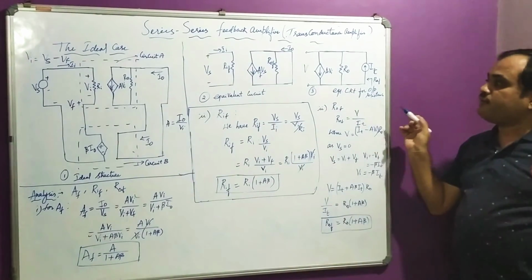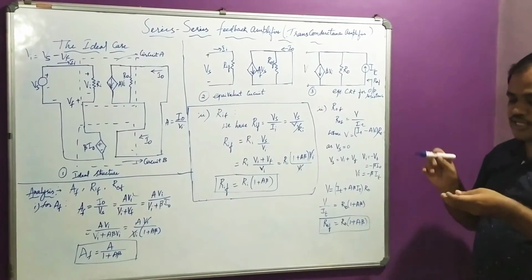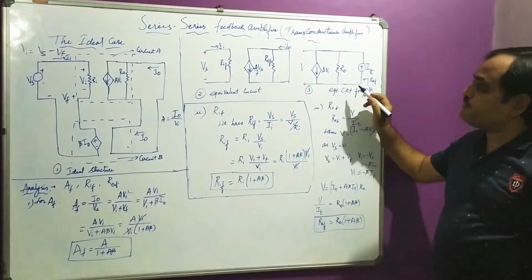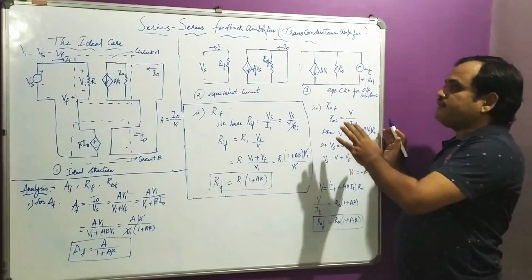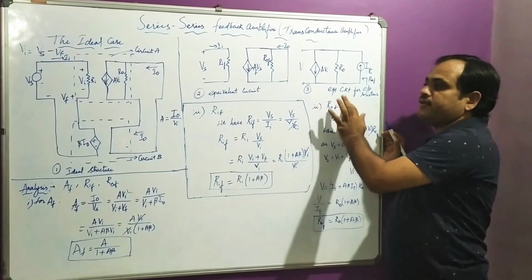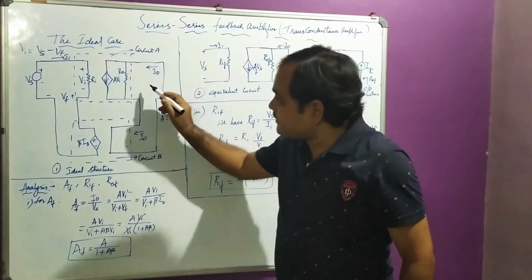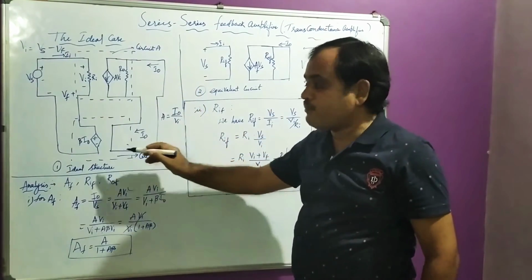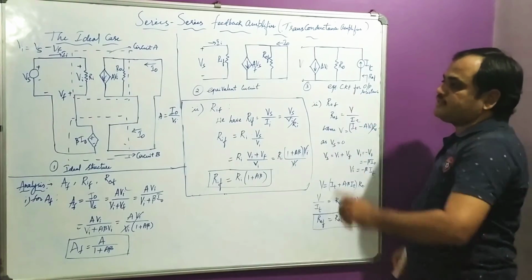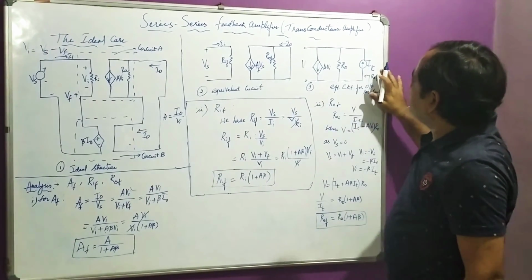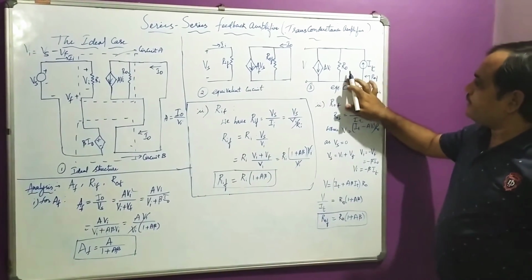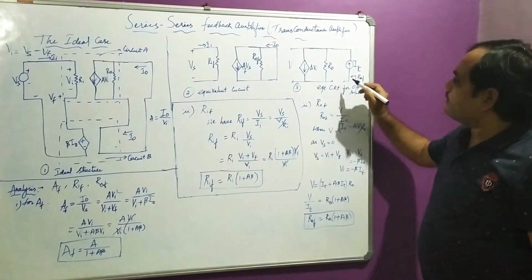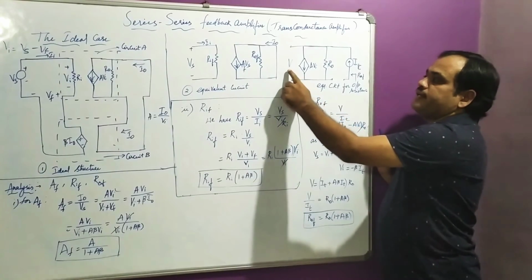Now come to the third one. This is the most important one. This changes from voltage amplifier, that is output resistance with feedback. There we have considered Thevenin's equivalent circuit. Here we are considering an equivalent circuit as current series. Current is connected in series, that is, output current is going to be sampled in the form of series. So we are going to consider a test current which is obtained from breaking the circuit, due to which I am going to get a terminal